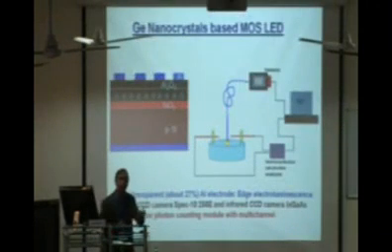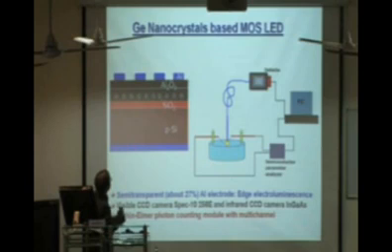Of course, for device people, the electronic engineers, you will not believe this photoluminescence. They say, can you give me some device, I will put a battery and the light will come on. That phenomenon is called electroluminescence. You apply the electric field, and if you get electron hole recombination, then the light comes on. So in fact, we have made a structure with these quantum dots in a different oxide matrix, like an aluminum oxide matrix in this case. And this silicon dioxide is a very thin layer which acts as a tunneling barrier, so that the holes can be injected from this side and the electrons can be injected into the quantum dots from this side. Then we try to detect this emission with a fiber optic coupled system.